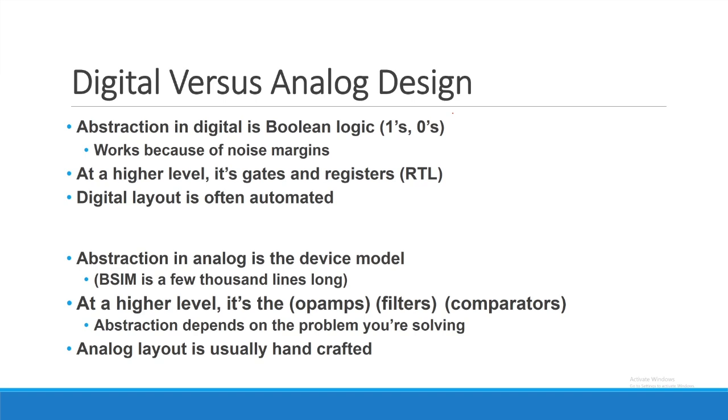What's great about that is that it lets me really abstract my design and ignore a lot of the details of what's happening. So I can say my abstraction is, let's say, either gates or registers, and I can write some sort of hardware description language. Then based on that description, I can come up with all kinds of rules and techniques to automatically generate my entire design.